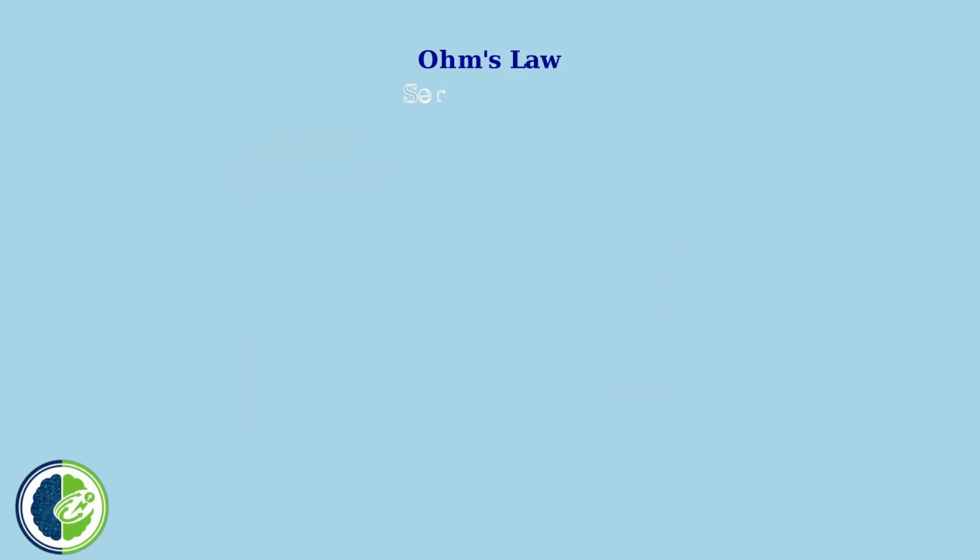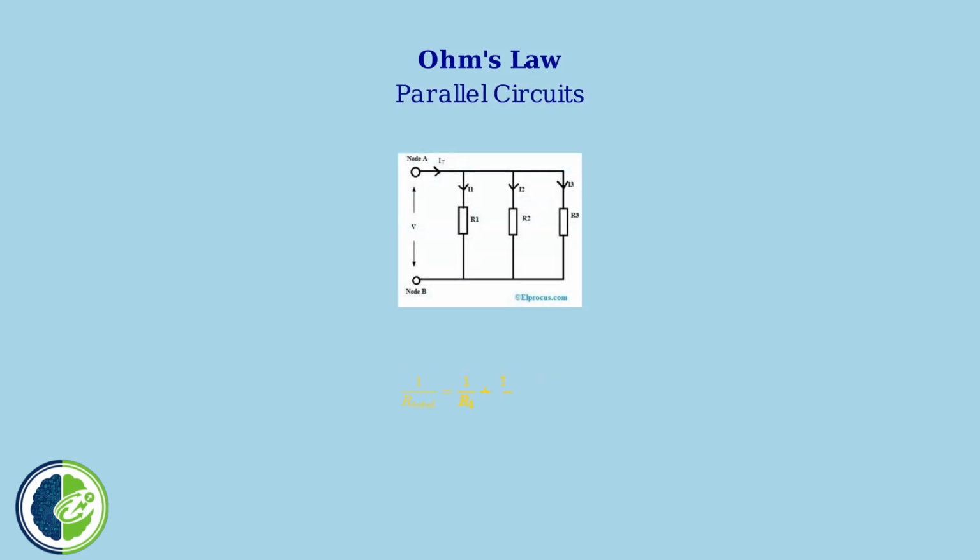Now let's explore how resistance works in series circuits. In a series circuit, resistors are connected end to end, and the total resistance is simply the sum of all individual resistances. Parallel circuits are different. Here, resistors are connected side by side, providing multiple paths for current. The total resistance calculation is more complex. We use the reciprocal formula.